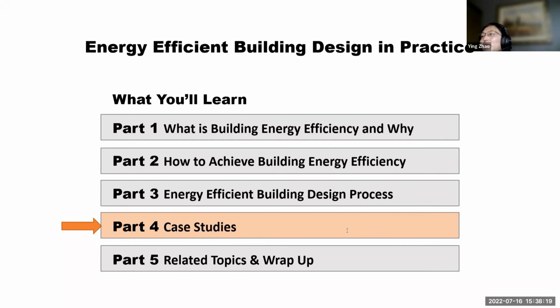What is an air-to-air heat recovery unit? Yes, we just talked about that. The first air is the exhaust air, the other air is outdoor air. You exhaust air out and outdoor air goes in, so you recover the energy from the exhaust air. It's actually an exchange.